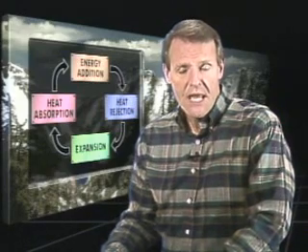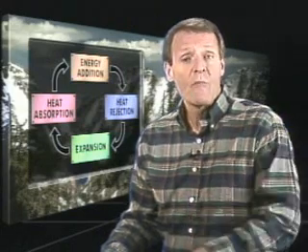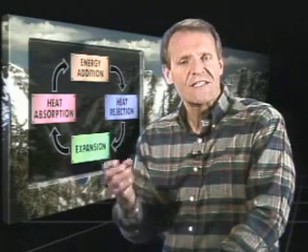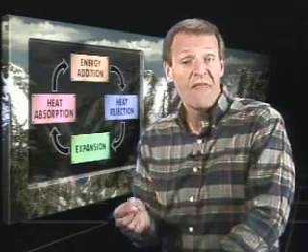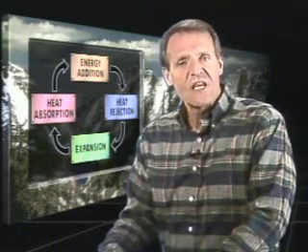The primary purpose of a refrigeration system is to remove heat from a substance. In most cases, removing heat lowers or maintains the temperature of the substance. To lower or maintain the temperature, a refrigeration system must be able to continuously absorb heat and then reject the heat from the system. This is done through several steps in what is called a refrigeration cycle.